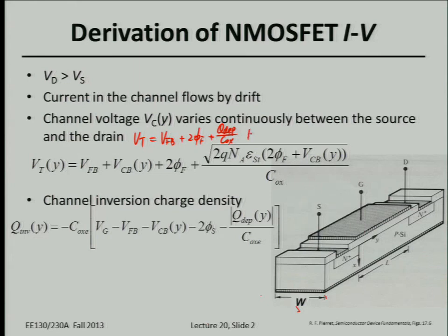And two-terminal means you're only able to generate the one-dimensional potential profiles vertically across this structure. Basically, that's along the x direction, right? That's how they modulate the electrostatics of the device in the two-terminal MOS capacitor. But things are going to be a little bit more difficult here. Right now, if we have another two terminals, which are source and drain, and we keep applying another voltage laterally across the MOSFET channel, then due to a very simple superposition rule of the potential profiles, we are dealing with a 2D potential problem, right?